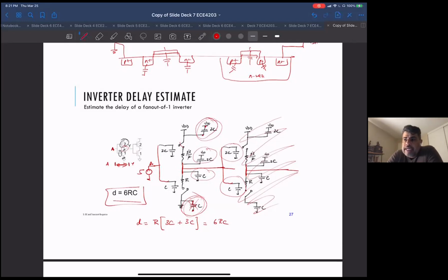It's because when you're doing analog design, you can do all sorts of crazy stuff and connect things to all sorts of crazy biases. You just don't really tend to do any of that in digital design because they are really dangerous techniques unless you're paying a lot of attention. You can change things around the substrates, for example. In a lot of processes there are so-called deep N wells, which let you even separate the NMOS substrates.